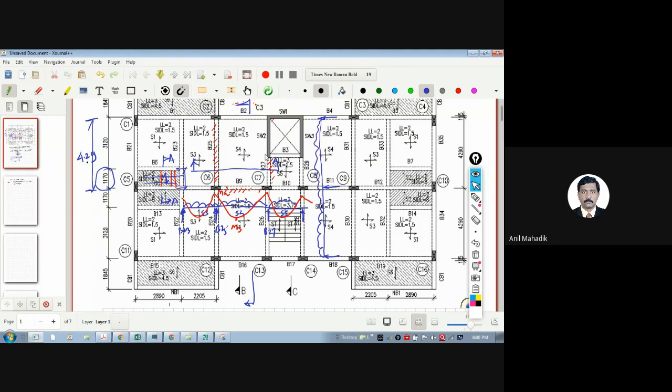So this is the load for S4. Then this is your B9 beam here. This is the loading diagram of slab. Please understand. Now here you can see as there is no slab over here, this is a discontinuous end. So we will have a bending moment 0 here, and then I will have a moment like this. Did everyone understand?